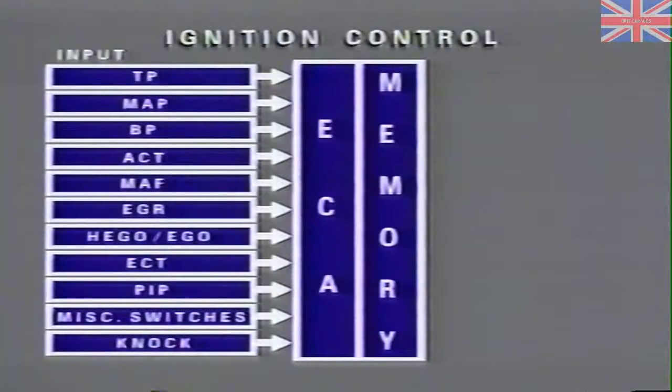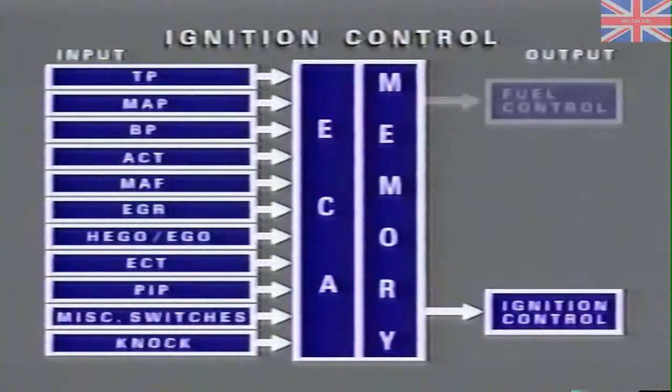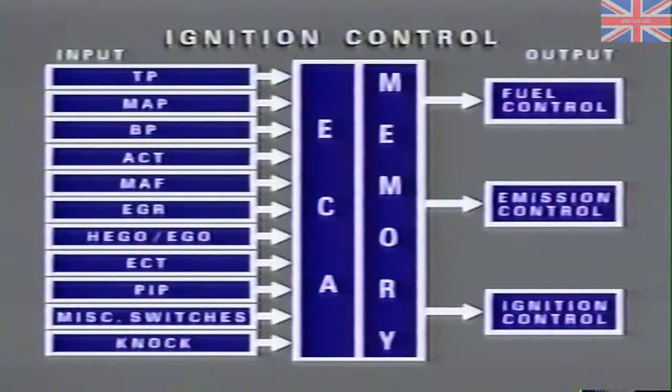The ECA, or Engine Control Assembly, utilizes the various sensor inputs, processes the information along with pre-programmed operating instruction memory and calibration memory from a calibrator, makes a decision, and responds to various controlling devices in either the ignition system, fuel system, or emission system.